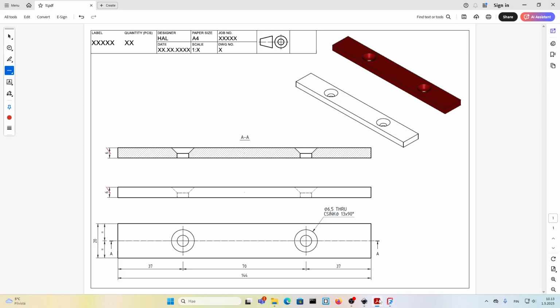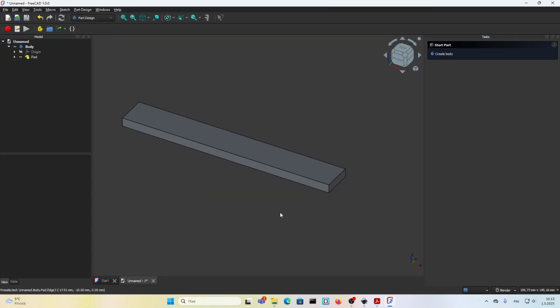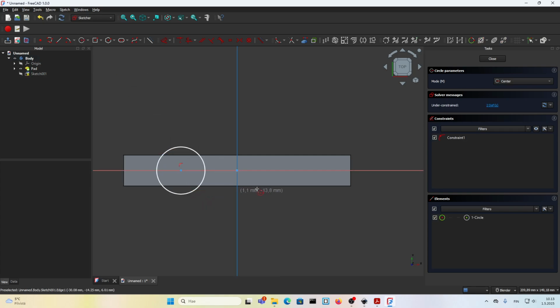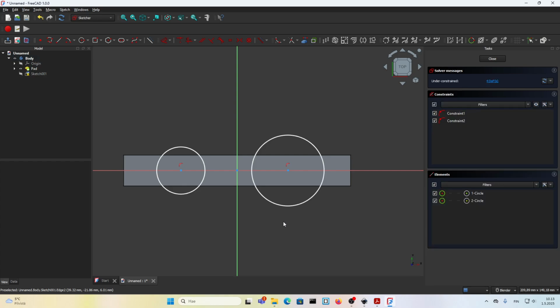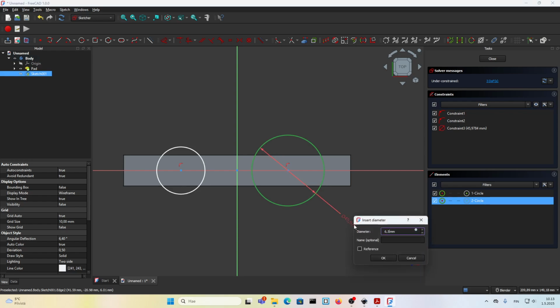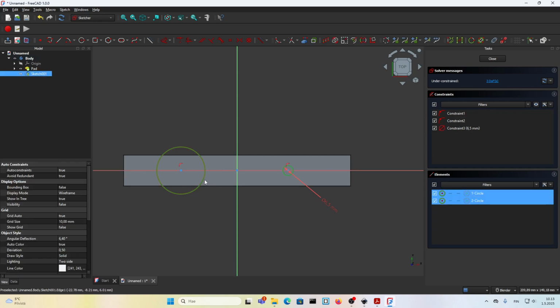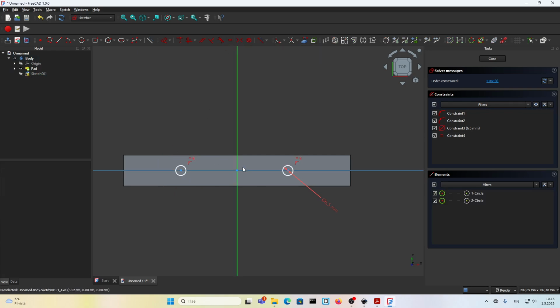We are here. Let's go back to the drawing. We can see we have two holes, countersink holes, 6.5 millimeters through. Let's make this. And you can see the dimension from the center, 35, 35. Click on here, create a sketch, circle tool, first circle, second circle, right click, exit the tool, D from the keyboard for dimension. Let's make this 6.5. Right click, exit. Also, let's make them same size. From here, choose them both like this and constrain equal. Now they are both same size.